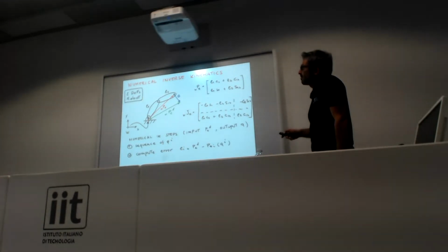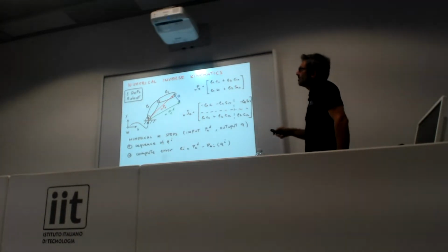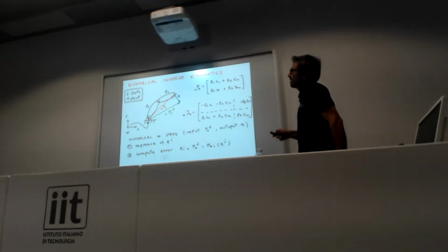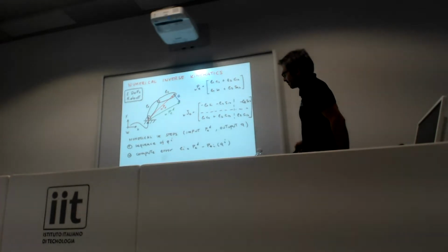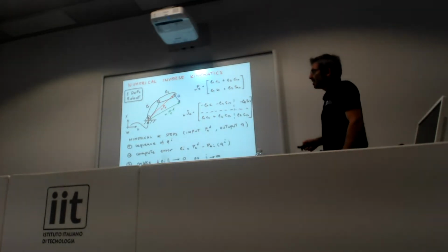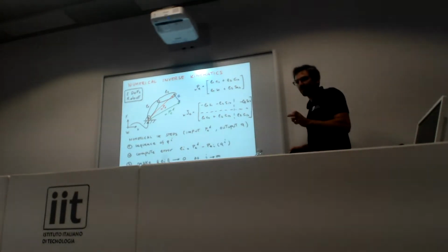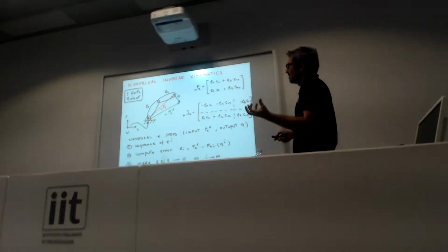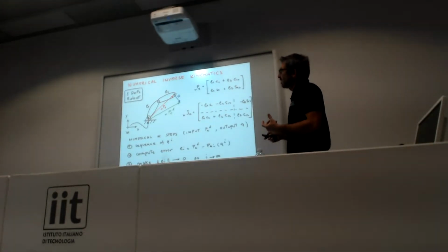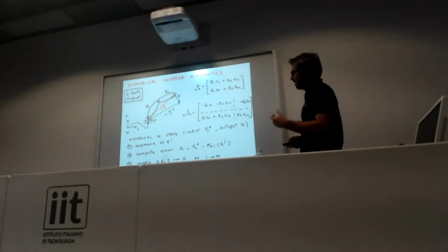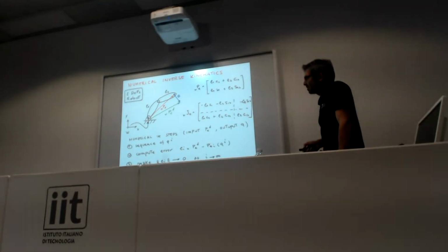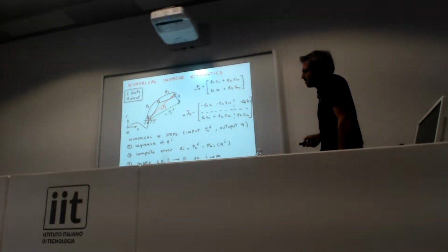Let's say we start from a default configuration and compute the position of the end effector; this position will be different from the desired one, so we compute the error between the two. The idea is then to make this error go to 0, and when it does, the set of joint positions will be the one corresponding to the desired end effector position. In the end, the error never goes exactly to 0. We care that it becomes sufficiently small, below a certain tolerance.